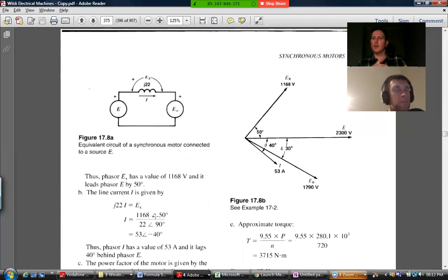It's best to leave them in polar format. Because when you divide, you subtract a 90 from a 50 and you get a minus 40. When you multiply, you actually end up just adding the numbers that are in the two phases. You add their angles, but when you divide one by the other, you subtract the bottom one. So you get 50 minus 90, you get minus 40.